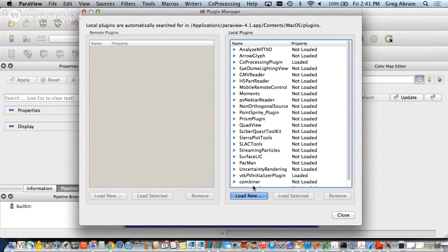In Visit, if you write a data loader plugin, you can also compile it offline. Of course you can. That's the whole plugin concept; you don't have to compile the whole binary. I had that with Visit. I was trying to use a reader that Dave had written a while ago for Enzo data, but it was slightly different because it included ghost zones. I couldn't get Visit to recognize the other one, so I ended up just recompiling the whole thing.